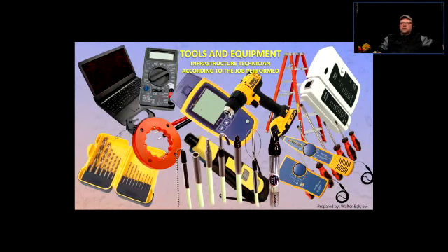any kind of data wire is going to be a failed link due to length, okay? Because you can only have a certain length when it comes to data cabling. All right, and it's going to perform light duty frequency response and signal response tests, okay? And it's going to qualify the link as, let's say, Cat5e or Cat6 or whatnot.